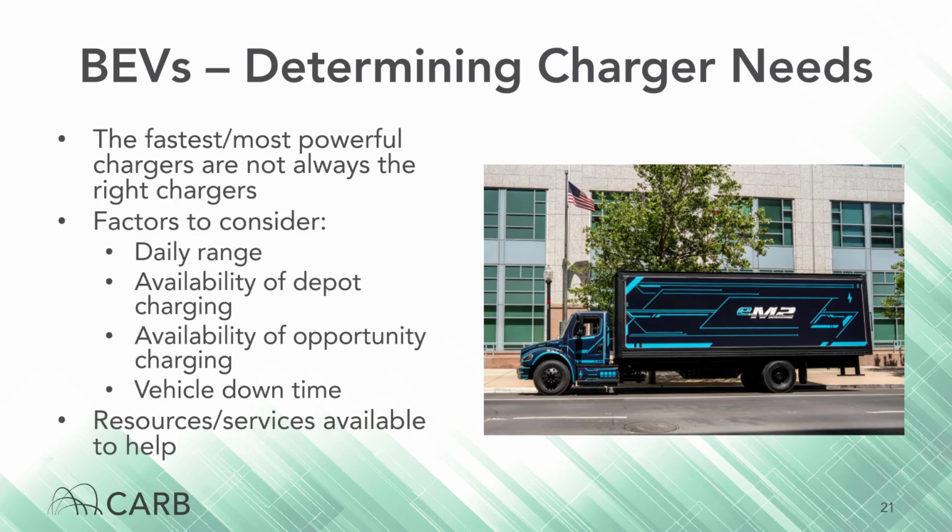So let's recap. Again, the fastest, most powerful chargers are not always the best chargers or the right chargers for your needs. Determining how much downtime a vehicle will have for charging, how many opportunities throughout the day or route it will have for opportunity charging, the availability of depot charging, and the daily range a vehicle will go are all factors that can determine how powerful or how many chargers you may need. There are online tools and resources available to help, as well as services offered to provide personalized strategies for determining what will work best for your needs.